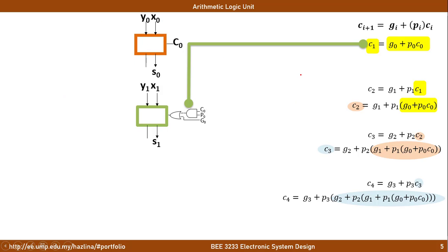Look at this stage in which this carry-in is being predicted not within this bound but also at an earlier stage, in which the carry-in for the first cycle is being predicted by the C0, P0 and G0 at the first addition.